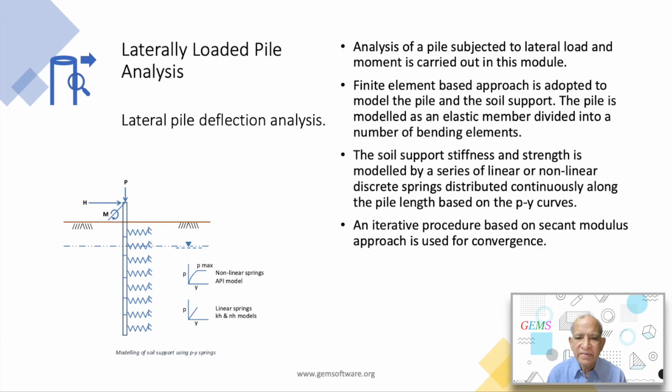Lateral pile analysis using PY curves. The pile is discretized into a number of bending elements. The lateral soil support is modeled by a series of lateral springs represented by PY curves along the pile length. The parameter P is the lateral soil resistance per unit length of the pile and Y is the lateral displacement. The software can be used for developing PY curves for all layers. The following methods are available for constructing the PY curves.